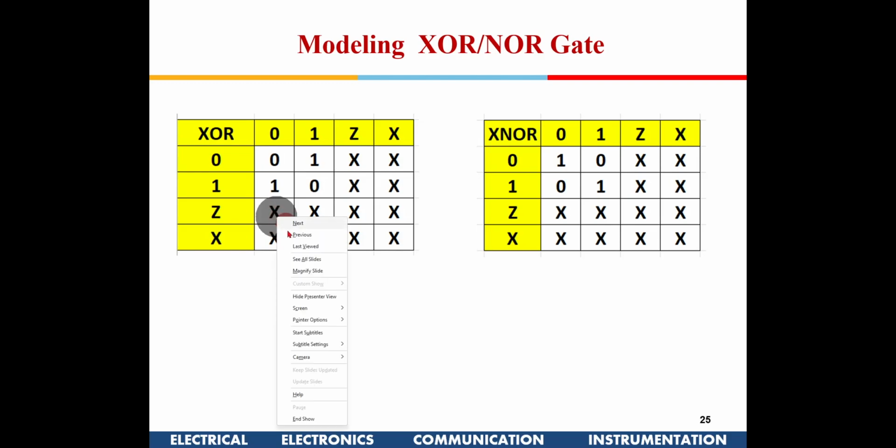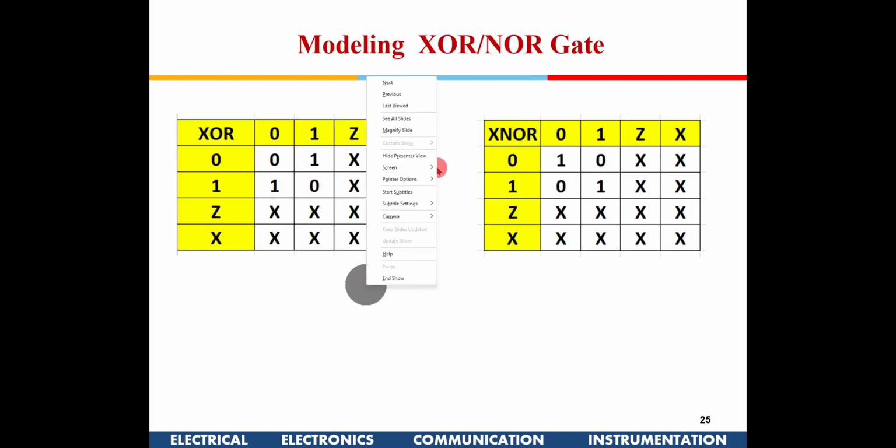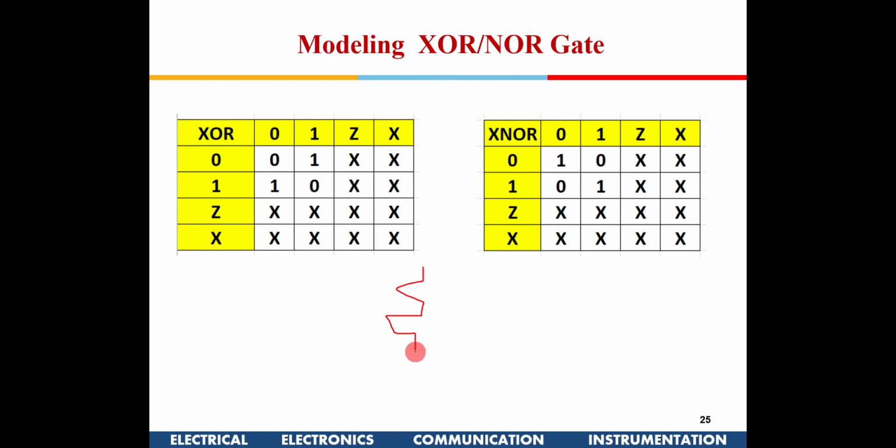Sir, if you see the transistor implementation, right? If I have some gate, a NOR gate for example, right? Even if this is left open, this is like applying a 0, right? Here it will never go to Z.